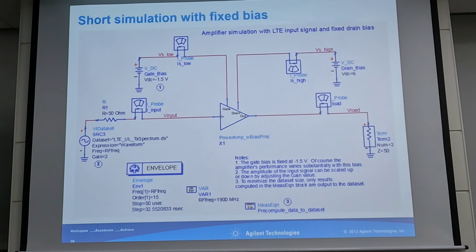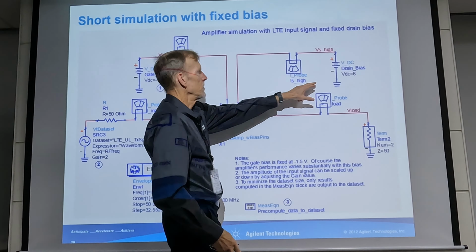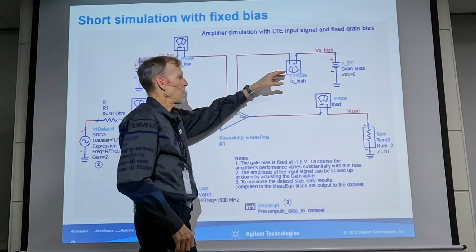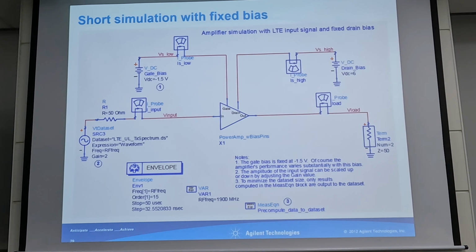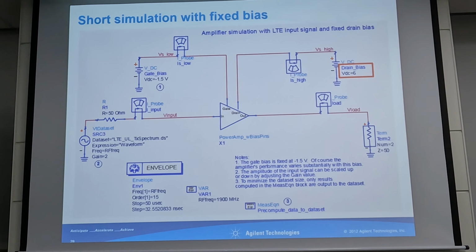But I have simulations for comparison. I think you need to simulate the PA under constant drain bias. So here this is a fixed drain bias, so I think it's useful to compare the results against this condition, the simple condition. The envelope tracking should improve performance.